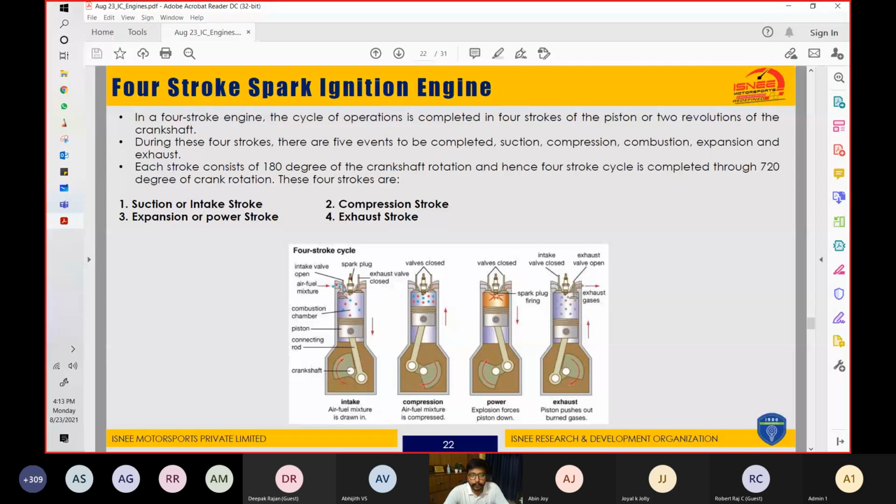This is the intake valve. We understood from our previous discussion that the valves open only when they are allowed to. This is a cam and camshaft mechanism that operates the valve timing, that lets the engine operate its valve whenever the timing is arranged for, and the duration. Like for how much duration it is to be kept open, and after that